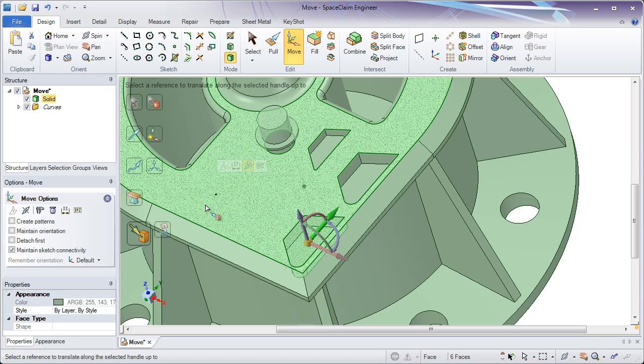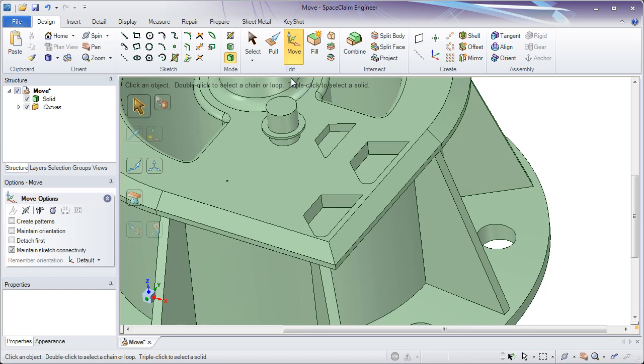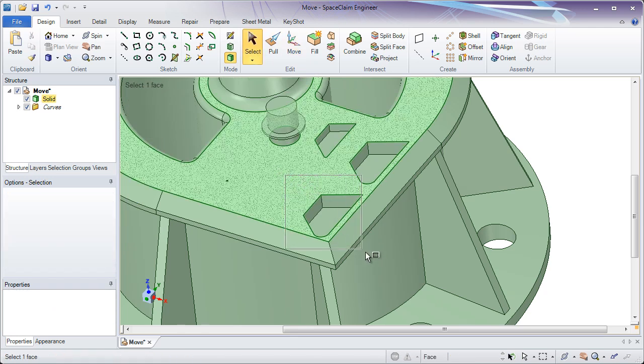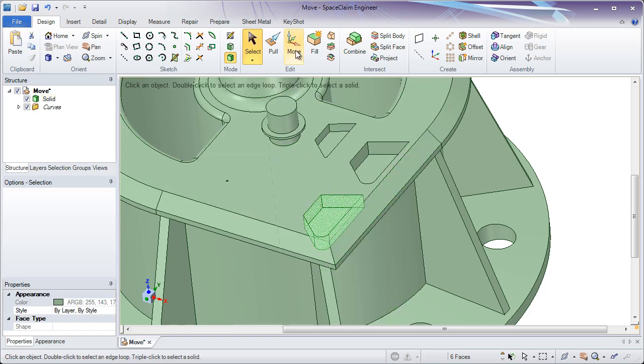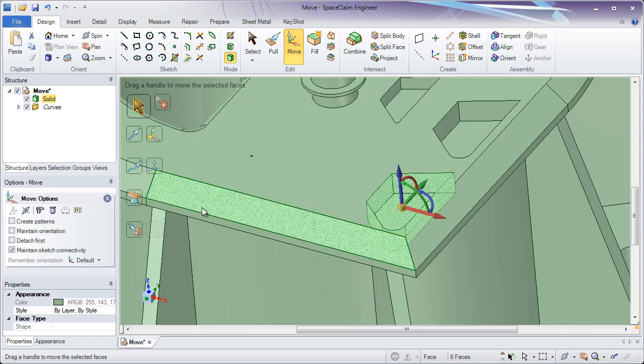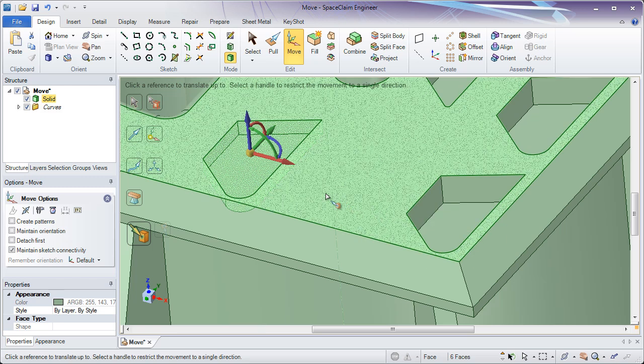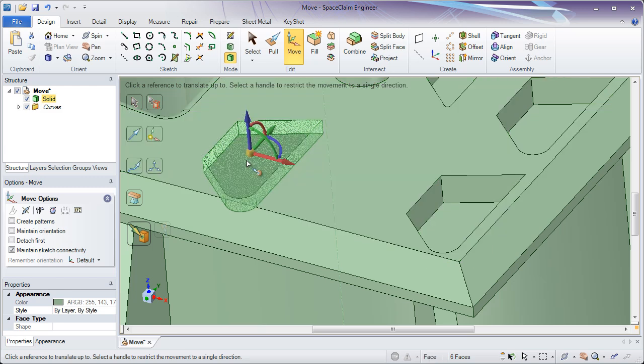And one thing I want to show you before we go is to remember, if you don't pick a direction for the Move tool to go, it's going to try to move it up to all locations at the same time. For instance, if I move and copy by holding the Control key up to this point without picking the red handle as a move direction, notice what happens is it moves it up to that point in the red direction and the blue one at the same time. Up to will always try to move in as many directions as you allow it to.